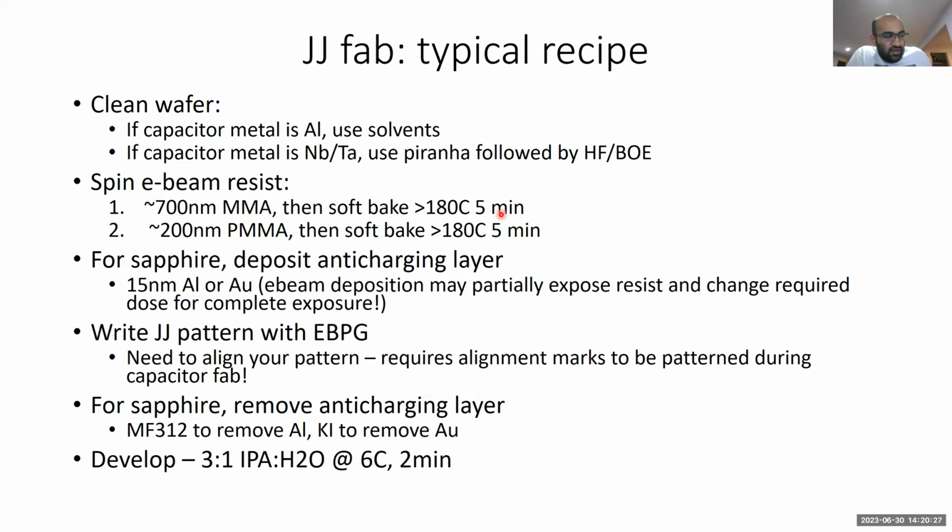As far as the temperature, humidity, and environmental conditions, they all matter, which is why we store our resist bottles in the clean room, which has a well-controlled temperature and humidity at all times. Yeah, I would imagine that for e-beam resist in particular, you don't want them to come into contact with water or moisture, because that can ruin the exposure and development properties. So you want to make sure that the humidity it's exposed to is well controlled.